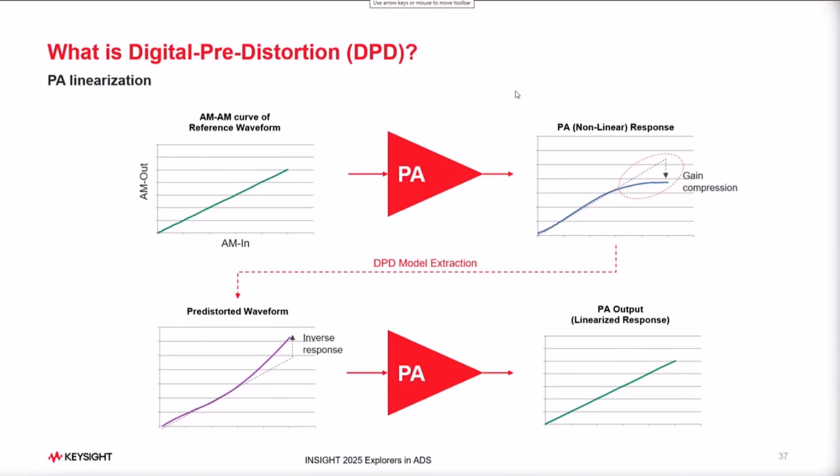Remember, depending upon how you do PA design, some designs with the same device may not be able to linearize much. Even if you employ DPD, your ACPR or your EVM will not improve to the number you are expecting. Every design is different. Every topology is different. Every device is different. So whether you do DPD or not, sometimes you still need to do this analysis to prove that you have done an excellent design which will work in a real world application.